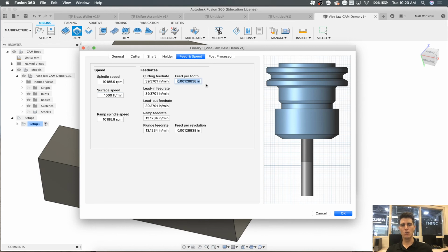On my feed per tooth, again, if you flip that sheet over, it will tell you that you can go up to 4, 5, 6 thousandths chip load per tooth. So that's going to generate a cutting feed rate of 152 inches a minute. Now, do I need to go that fast? No, not necessarily in this class. You certainly don't need to. And on the Haas, you won't be able to. So if I decrease my spindle RPM on the Haas, you're limited to 7,500 RPM. That's going to dynamically change your cutting feed rates.